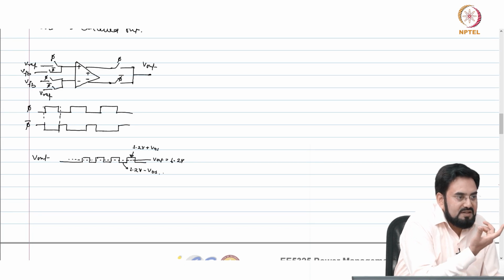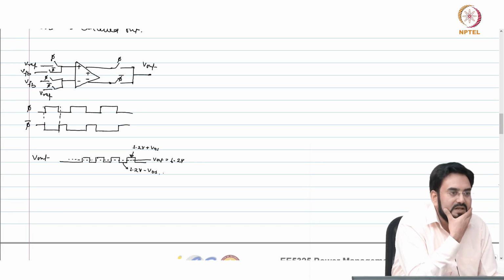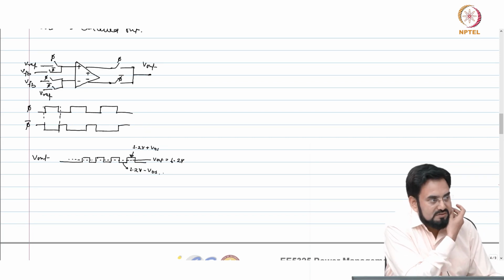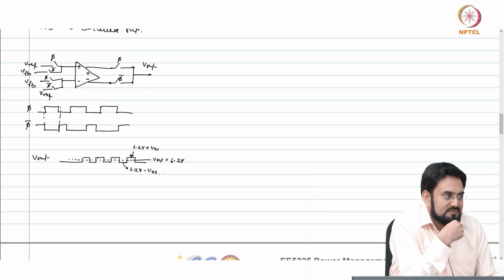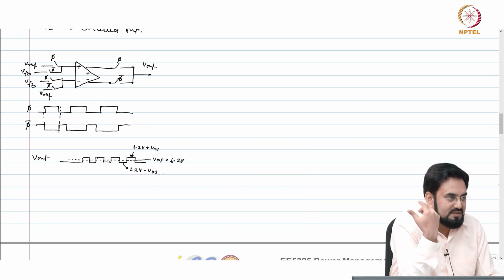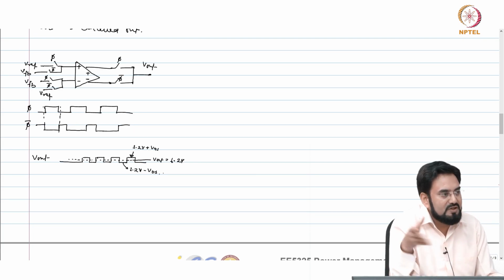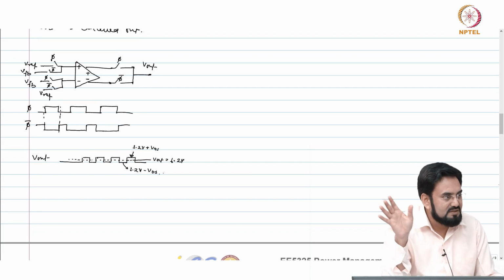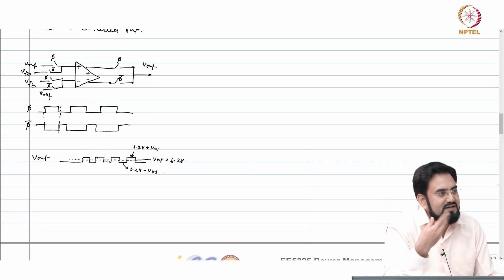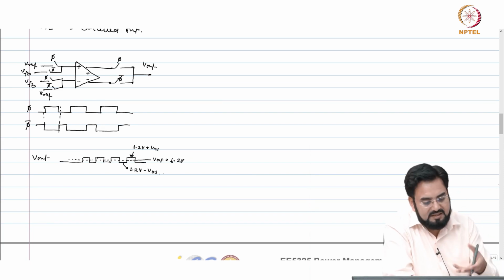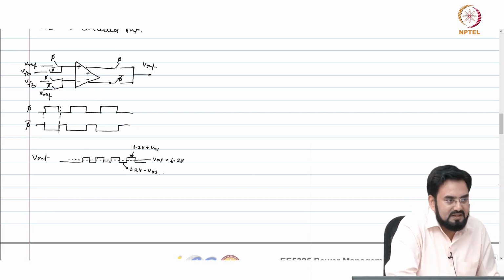So the only way it will work, you have to filter out this ripple by putting a low pass filter at the output, and then you can get it work. So use a low bandwidth low pass filter and filter these. Okay, and if your system is very, so let's say this output is going to some next stage which is by default has a very low bandwidth, then that will automatically filter it out. But if not, then you have to apply some filtering.